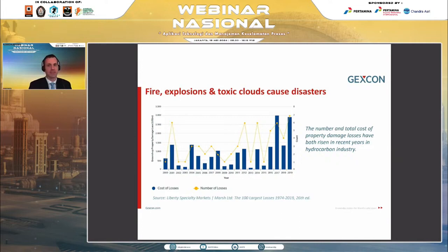However, the first one on the left has 9 820 millimeter pipes inside to simulate, say, one part of a refinery. And the second has 45 smaller 164 millimeter pipes to simulate another part of, say, the same refinery. It's important to note that they have the same blockage ratio, which is all that you can use as an input on an analytical model.